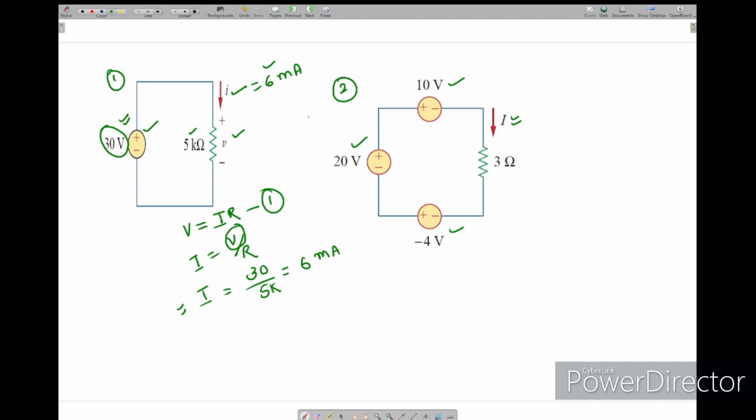Now see, in my previous lecture I explained about the KVL. So this is the current I, in this direction it is coming. So for a passive component, the terminal the current enters I will take as positive and the other as negative. Now I will write the KVL in this direction. So this is negative, this is positive. I am going negative to positive.